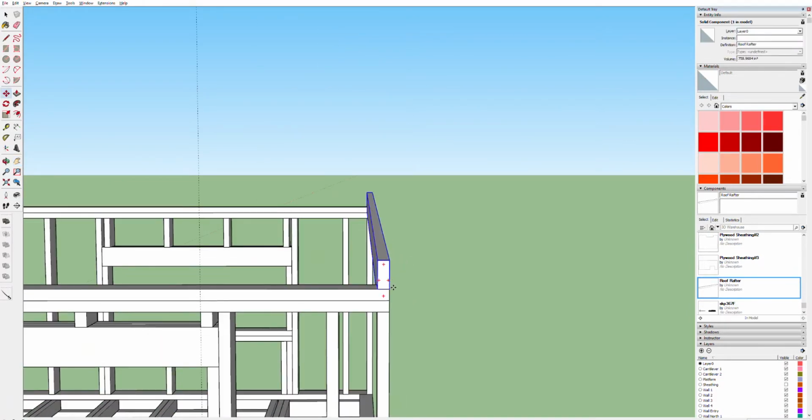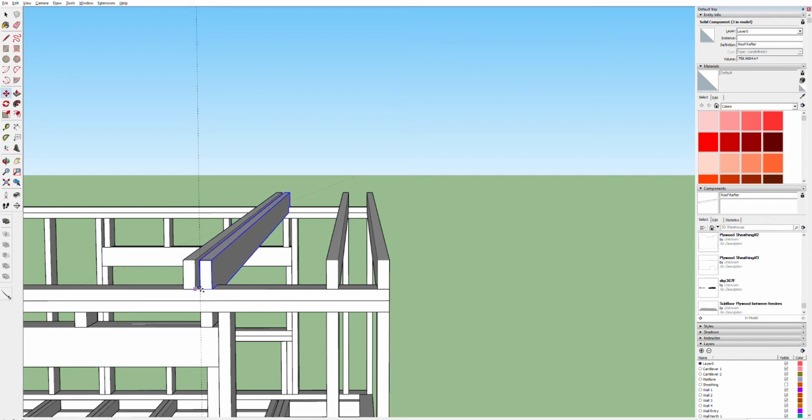I'm going to move this over, copy, lock to green, and I'm going to snap right to the stud below. And now this is going to get really easy because I can just do lock to green, and do 16, and that's going to line right up with this. So interchangeably, and just to prove it, we got 1'4". Interchangeably, I could then just go back to copying and locking right to that next stud, and that will also be 16. And just to prove it, there's the 1'4".